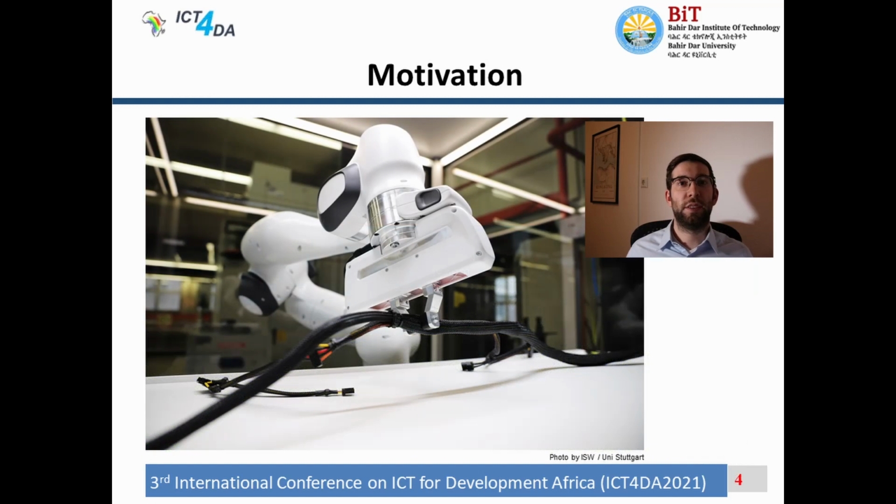Moreover, computer vision is already implemented in our manufacturing. Like in this case, where a robot uses a camera to detect the cable and decides where it needs to put the gripper to perfectly grip the cable. But this problem is static. The robot has enough time to take a picture statically and calculate where the object is and how it is rotated. What happens if we have a dynamic case, like for example with a moving cable or with some object which is driven around the manufacturing unit?